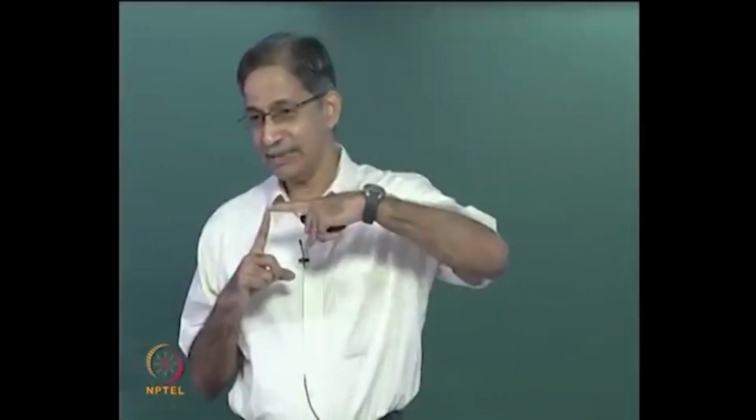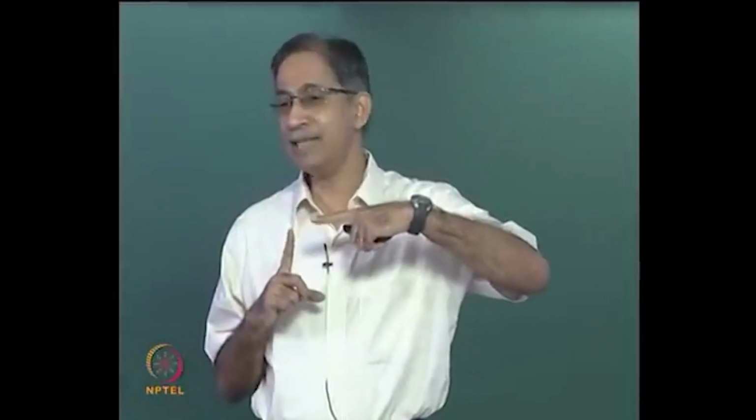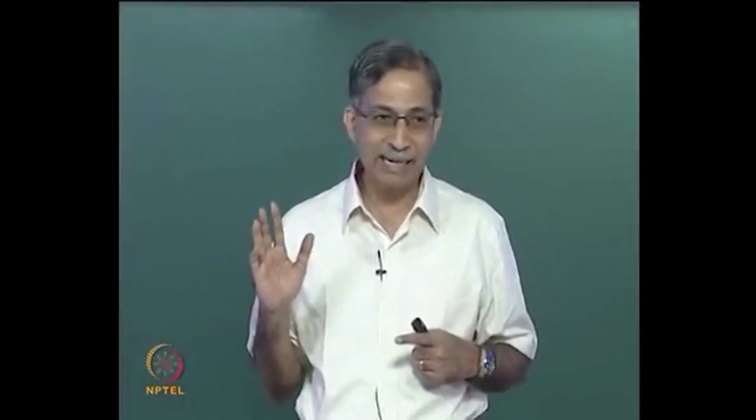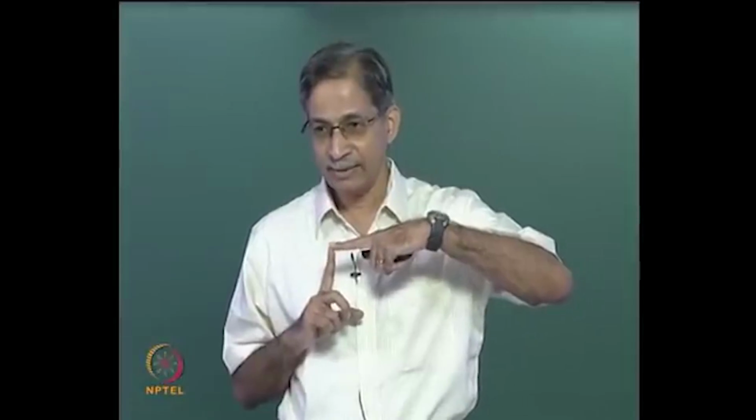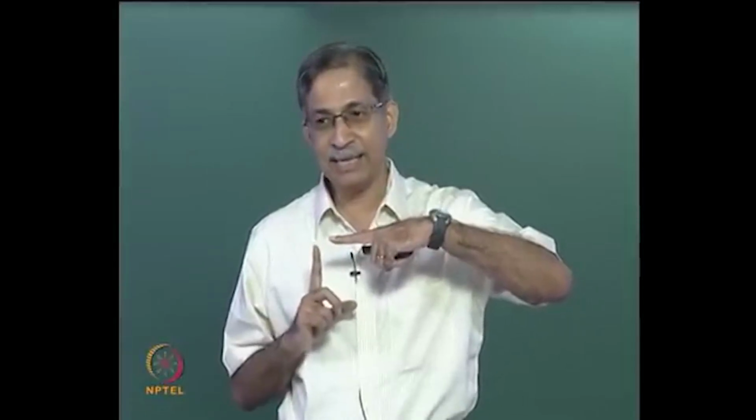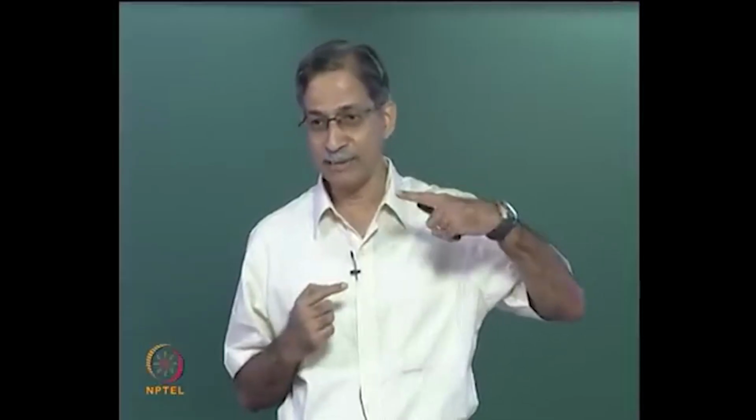I will tell you one way to understand. Remember when we talked of internal hinge, usually you have a parent-child relationship. Now clearly element 3 is a child. It badly needs elements 1 and 2 for it to hang on to for its own dear life, right? So the child cannot take loads when the parent is loaded. When the child is loaded, you will get something in the parent.